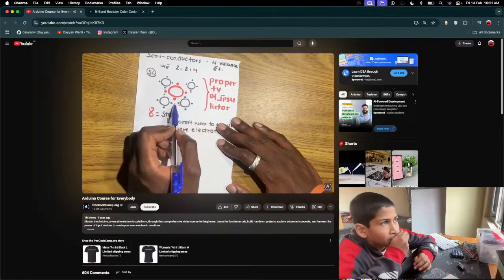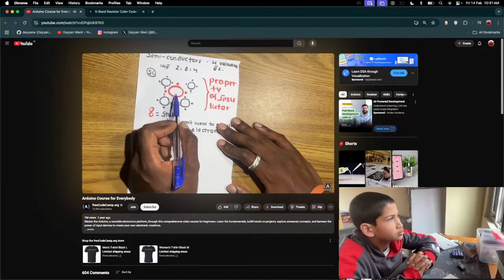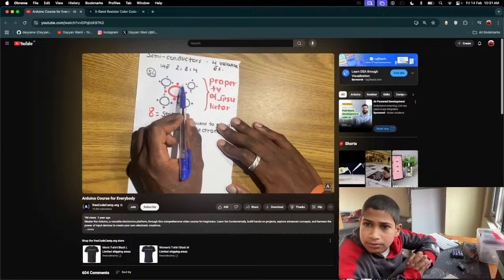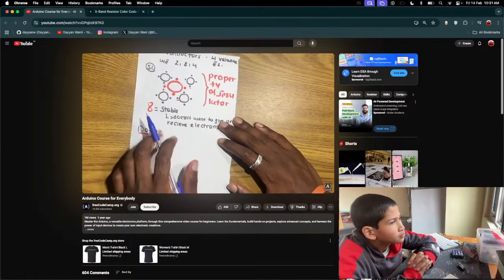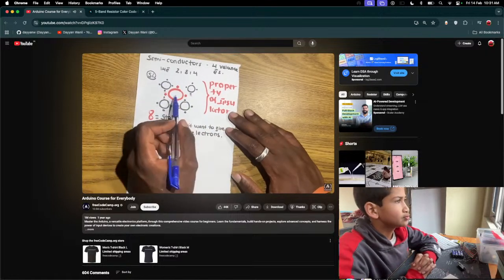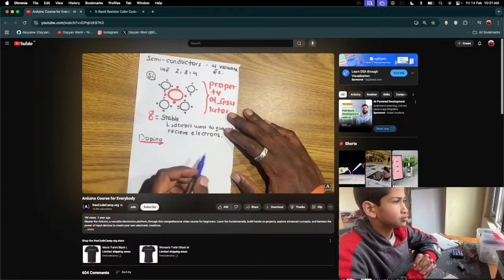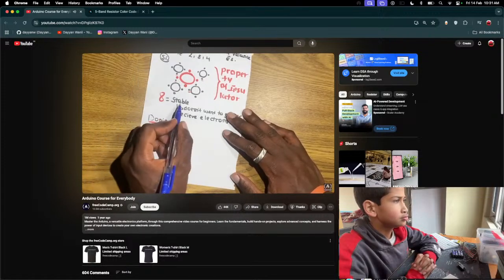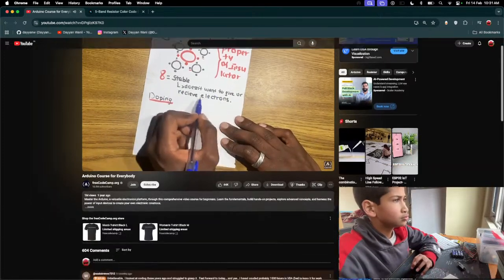One important thing that we see right here is the underlined dots. These are shared electrons. Electrons will be shared between each silicon atom and the central atom. If we add up the electrons right here, we have 1, 2, 3, 4, and we also have the 4 valence electrons that we already had from the beginning. So 4 plus 4 is 8. In this case, it's stable.